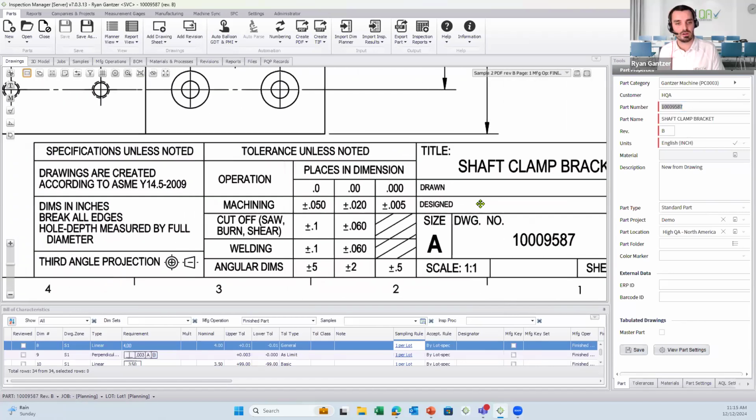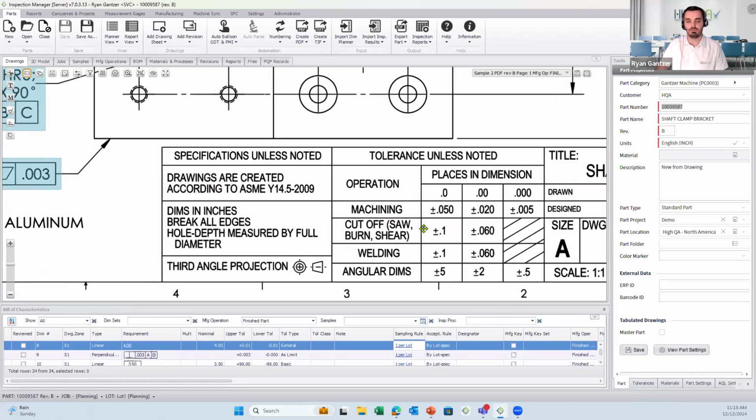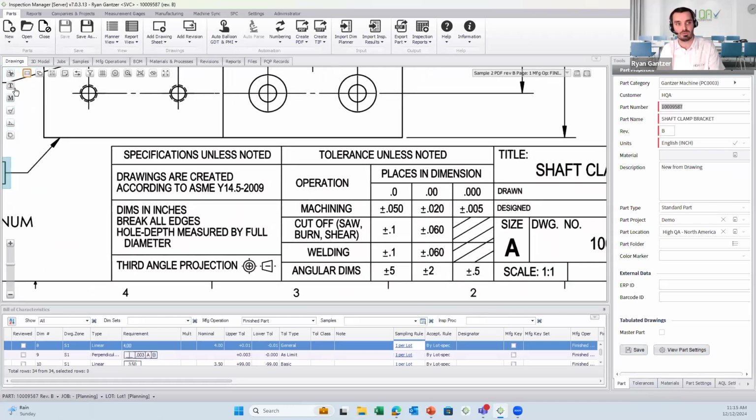Okay, moving on. We talked about the tolerances, where that's coming from down here: different tables, default tolerancing, based on these part categories that we have set up ahead of time. So for those of you that balloon notes or are required to balloon notes, we're intentionally not going to auto balloon notes, just because there's really no standard for that. They could be anywhere on the page. They could be required. They could be not. But another efficiency tool we have, highlighting it now, is this T icon to balloon notes.